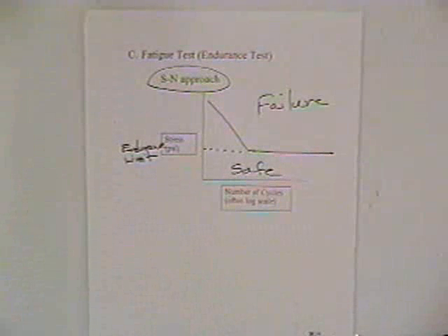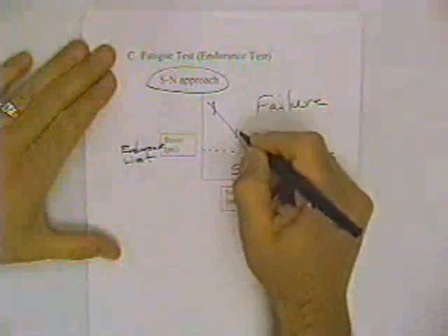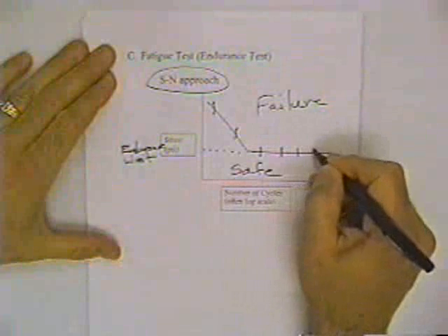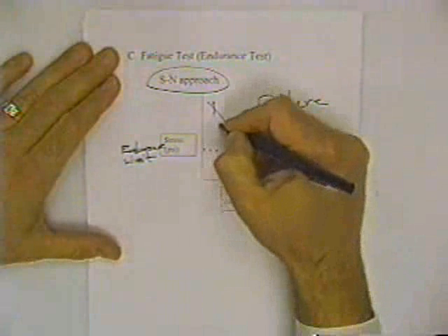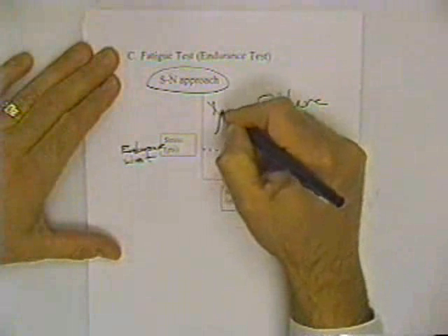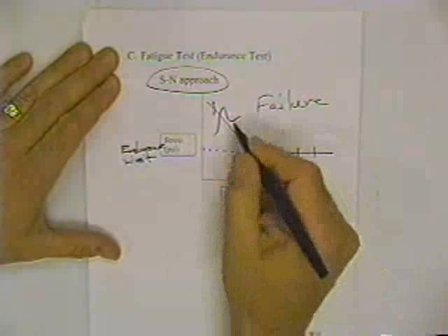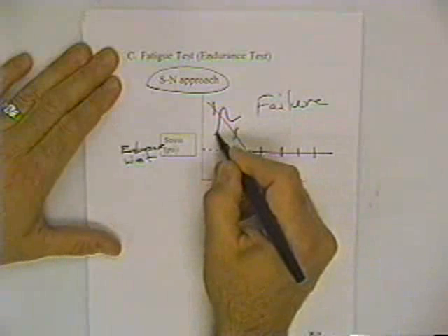Now, in actual fact, if you have stress risers, corrosion, wear, there are a number of things that can lower that endurance limit. And I ought to really be honest, shouldn't I? This is really a band region, and there is some statistical nature to the fatigue process, where a few specimens are going to fail on the high side, some on the low side.